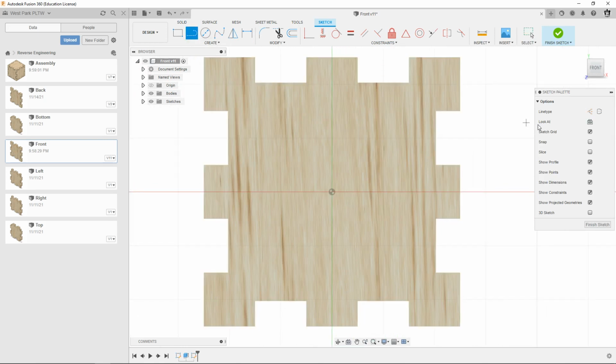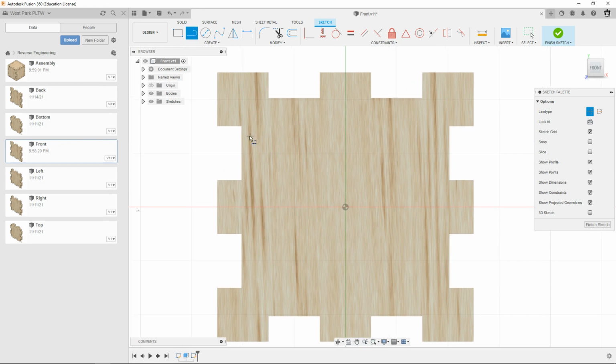What I'm going to do is draw some construction lines. They're going to guide my work here. I'm going to do a couple of horizontal lines first. For this horizontal line, don't let it get constrained. Don't let it go to an endpoint or a midpoint. I'm just going to draw it right about here, a little bit of the way down on that slot, and then go across.